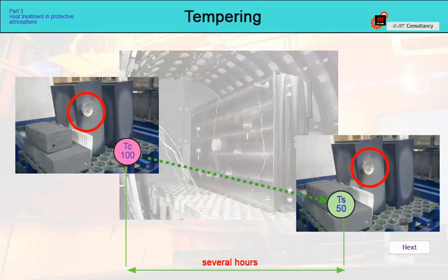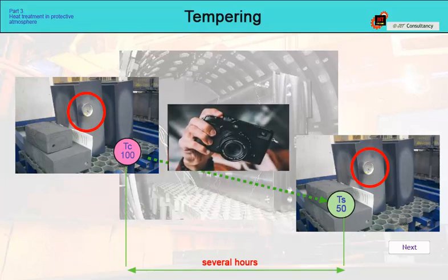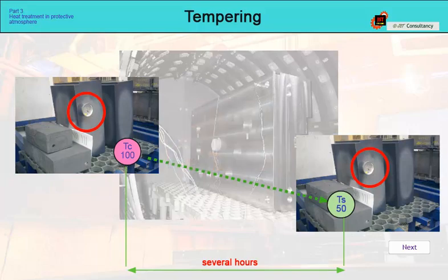To avoid future disputes between all parties involved in the process about the effect of this delay between quenching and tempering, this transition must be defined and documented. However, since the hardened inserts are already outside the furnace, this phase of the process is not part of the quenching or tempering cycle record.